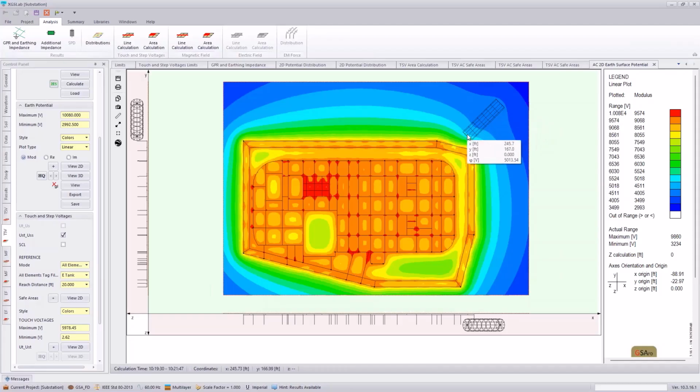As we get closer to the substation, the ground potential rise or the Earth's surface voltage is elevated up to 6,000 volts as you get right at this ground loop. That means that we're going to have several 1,000-volt difference between the voltage of our tank and the Earth's surface, and that's something that we need to mitigate. And one methodology for doing that is let's improve our grounding system performance, for instance. We already know we need to mitigate it. One simple, easy way to do this is let's account for our fault split factor.